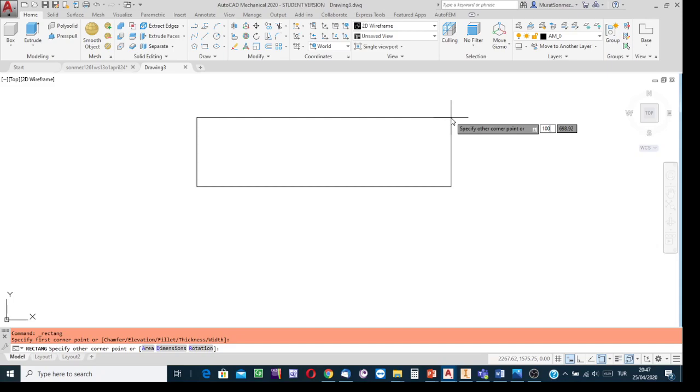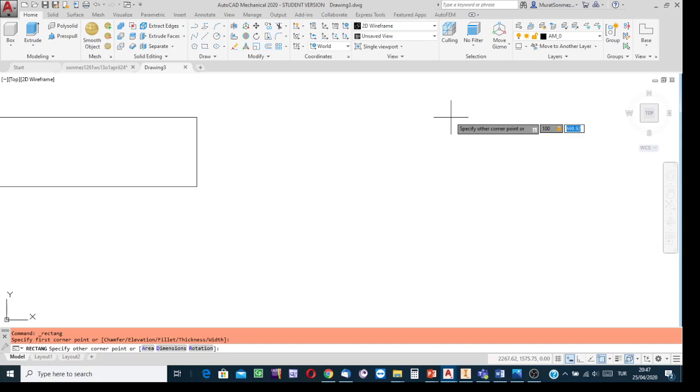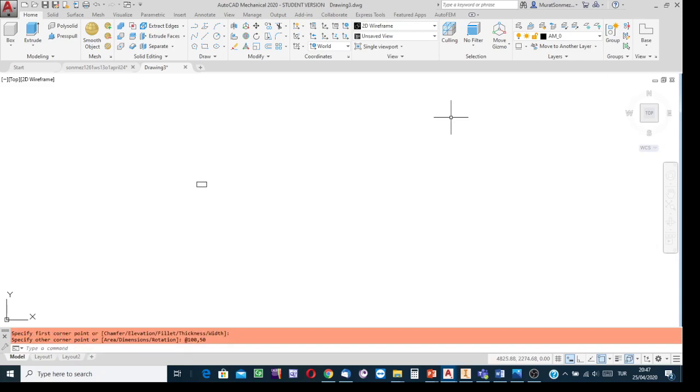Okay. Click the comma key and into this box write the delta y value. Delta y, since in my consideration it is the bottom side surface, corresponds to the depth of the prism. It is 50. Write 50. Press enter. Here is the rectangle. Relative to the size of the display screen, it may be small or very big. If it is small, you can scroll the wheel of the mouse and zoom in, zoom in. If it is too big, zoom out, zoom out.